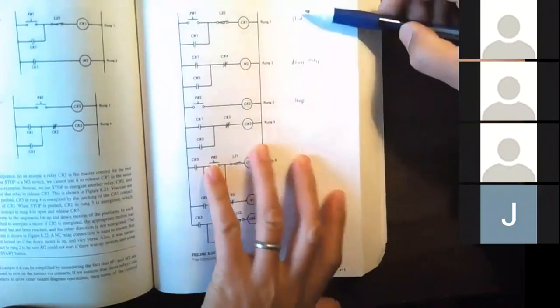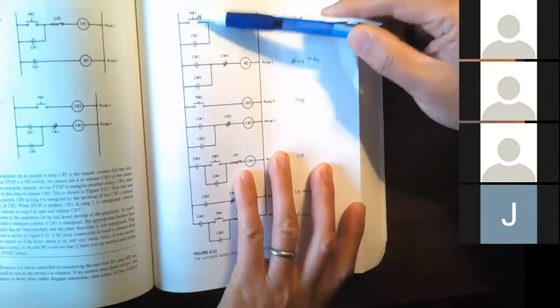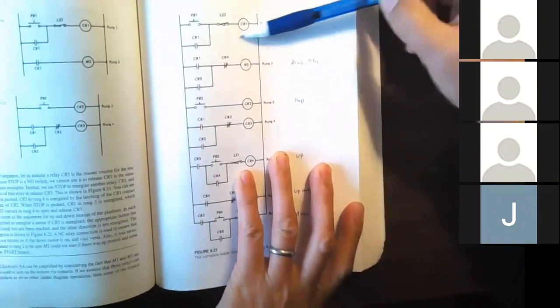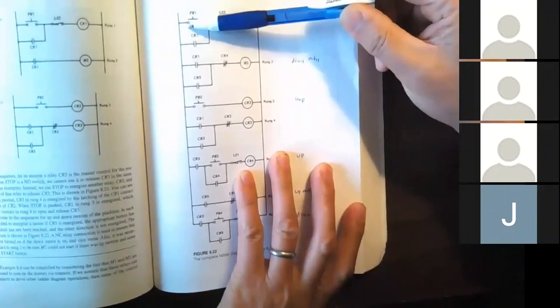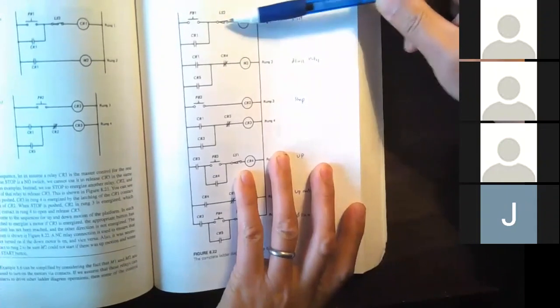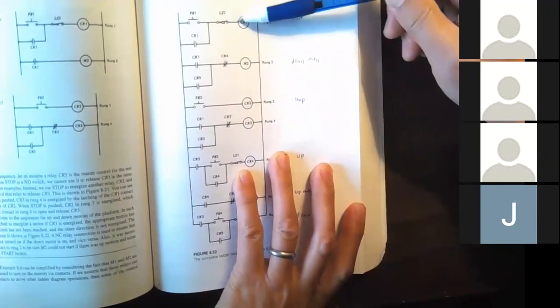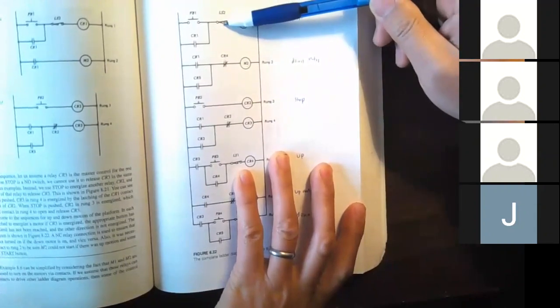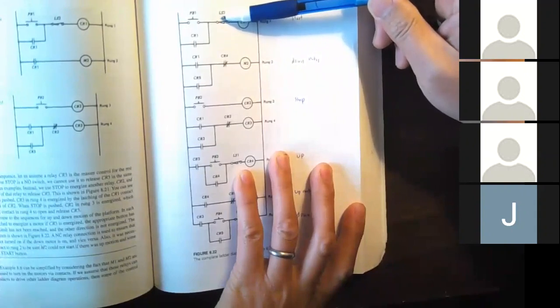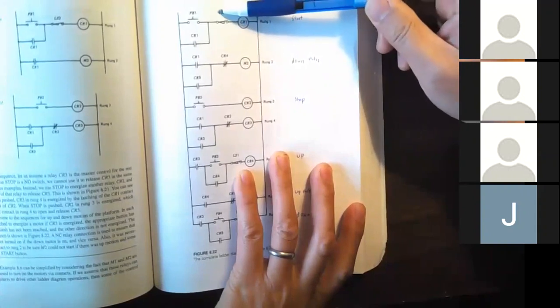So first, let's look at what happens when we push start button. So this is the start button. This is a starting latch. So we push start button, the start latch will latch, and that's it. The start button latch will disengage when LS2 is triggered. What is LS2? LS2 is the down position limit switch.